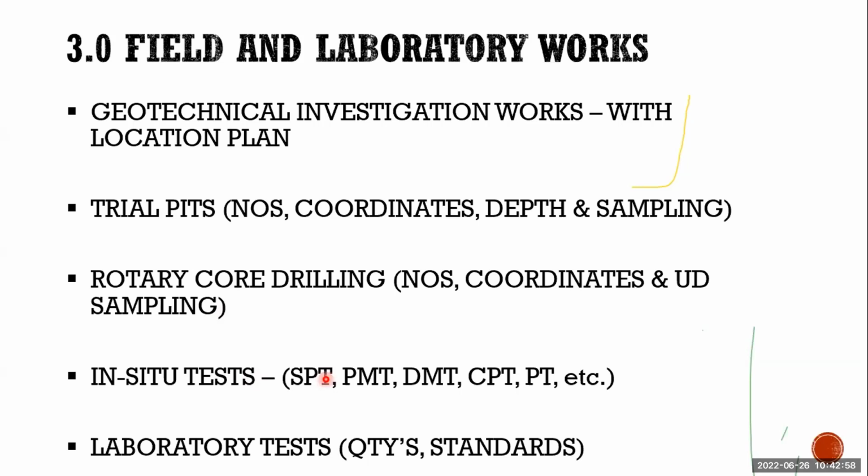For cohesionless soils, you have very loose, loose, medium dense, dense, very dense. And with the pressuremeter, you can determine in-situ stress parameters. The DMT, dilatometer, is also an in-situ test. You can do CPT, cone penetration test, percolation test, and so on. We have many varieties of in-situ tests. Based on the scope, we can include them in your report.